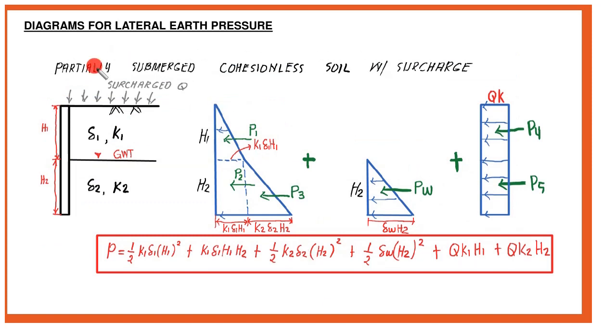And what if we have partially submerged cohesionless soil with surcharge? Ito naman, may uniform load tayo or yung tinatawag nating surcharge. The same pa rin yung dito sa dalawa, doon sa previous diagram natin. Ang inadd lang natin is the effect of the surcharge. So, yung effect ng surcharge natin is actually the coefficient of lateral earth pressure multiplied by our surcharge. Yun yung value natin dito.